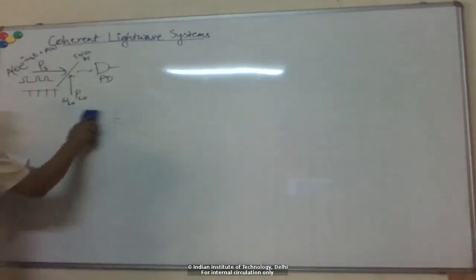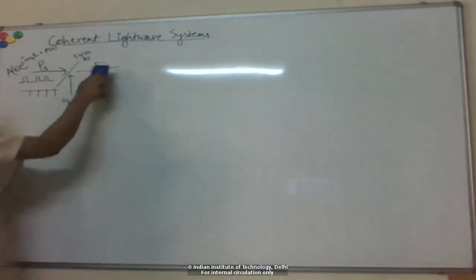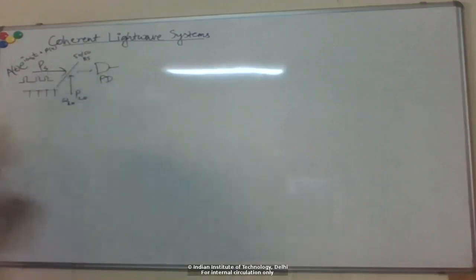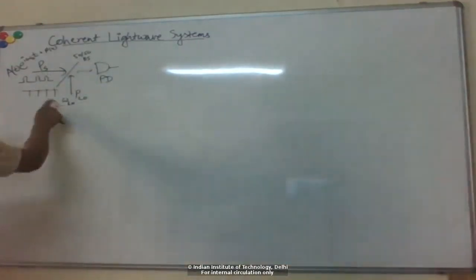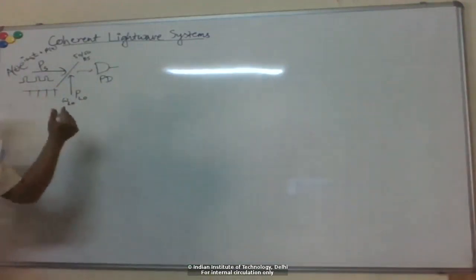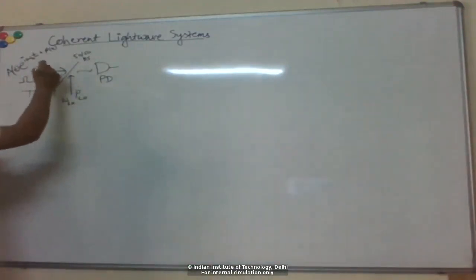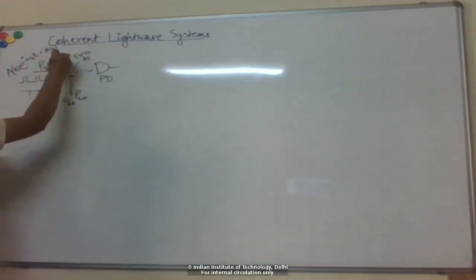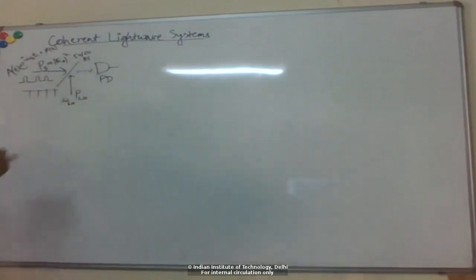Okay, so basically the addition that we've done here is that at the receiver we have another laser which is narrow linewidth with single frequency and close to the frequency of the transmitter. Again, the power is proportional to the mod square of the electric fields, right? Here, similarly.